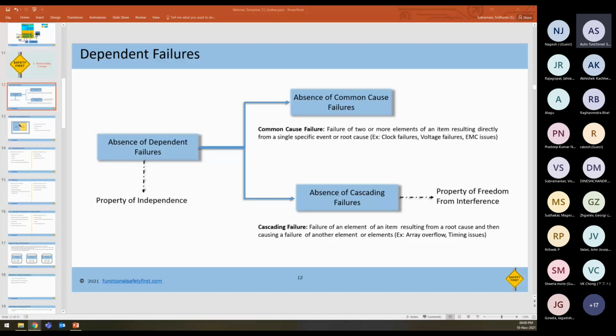So let's say we have a system with many different safety tasks, and for safety we have timing requirements, FTTI requirements, and sometimes functional timing requirements. To meet all this, each of the safety tasks needs to run at the configured frequency. If I decide to run a safety task at 10 milliseconds, I would want it to run anywhere between, say, 8 to 12 milliseconds. I would have to define that every safety task needs to run in the required periodicity for me to meet the FTTI requirements. Now this level of detecting whether the safety task is really running at the required frequency may or may not be detected by just having a watchdog.